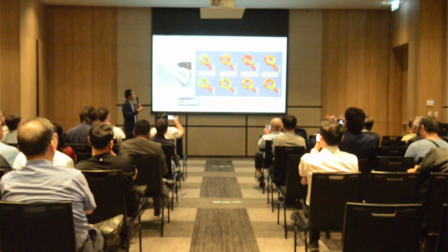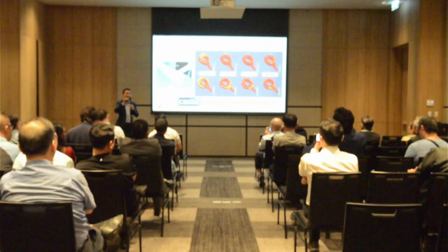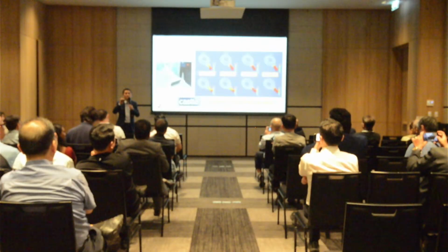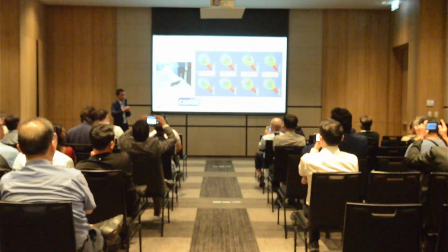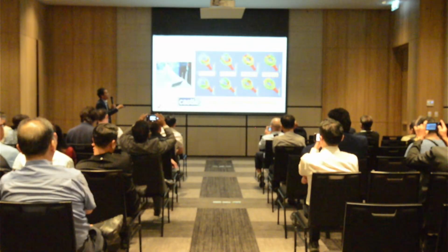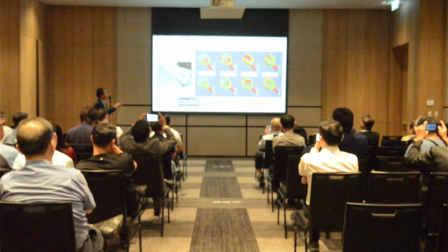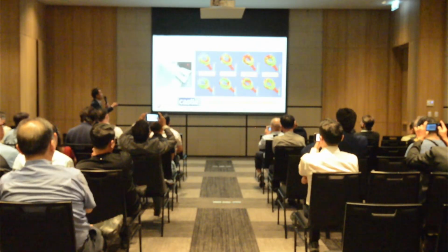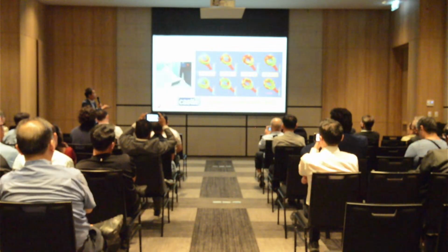Here I just use a constant viscosity because the feeding time is very short, normally 20 to 40 milliseconds. I use a constant viscosity with no change during feeding, just to show the difference. This one is about 3, and the unit is for viscosity: 3, 10 times, 100 times, 1,000 times. It's like honey, very high viscosity. They use the same speed.